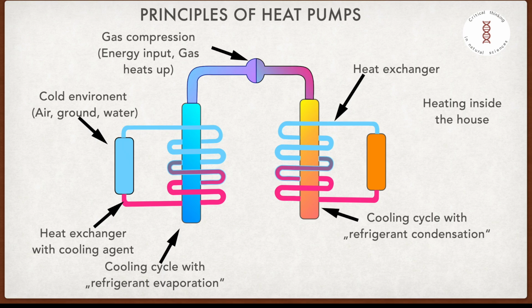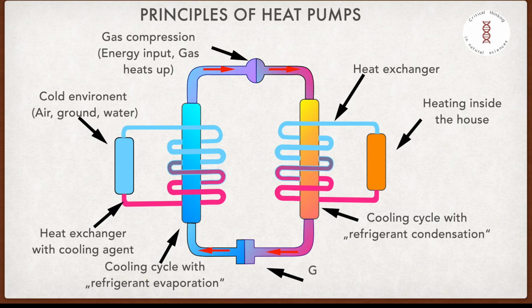That is the boiler of the house used to heat the house. And then during this process, when it releases the heat, the refrigerant condenses. And then after condensation, it is conducted to an expansion valve.